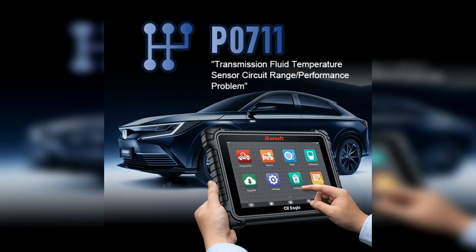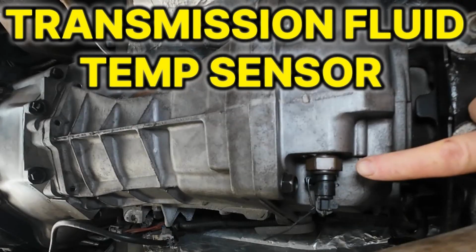Causes of the error: the P0711 code could mean that one or more of the following problems have occurred. Possible short circuit to ground in the TFT sensor signal circuit. Possible failure of the TFT sensor, internal short circuit. ATF transmission fluid is contaminated or low. Clogged or blocked transmission fluid passages. Mechanical failure inside the transmission. Sometimes the cause is a faulty PCM module.